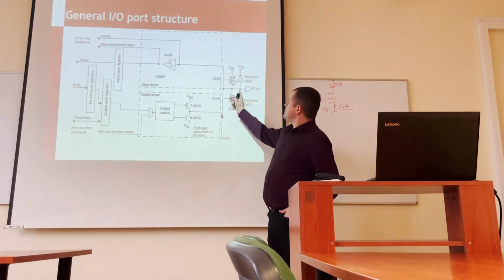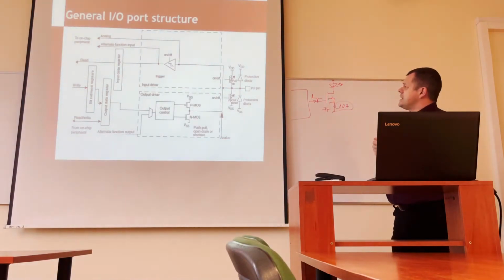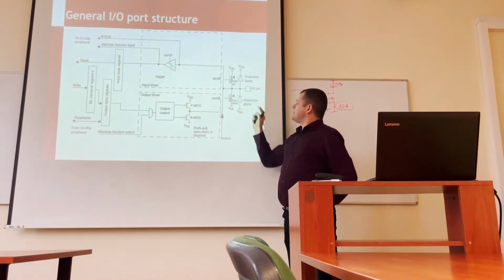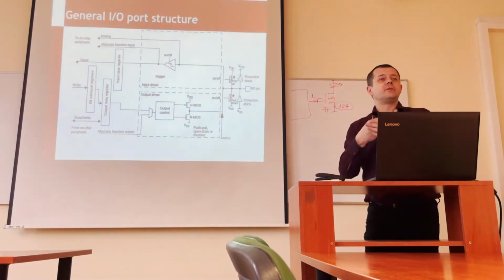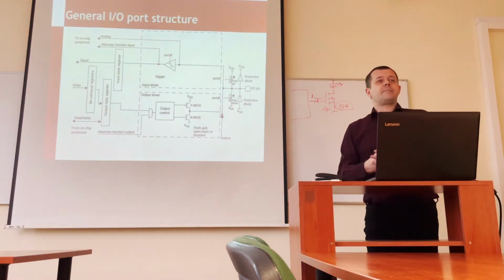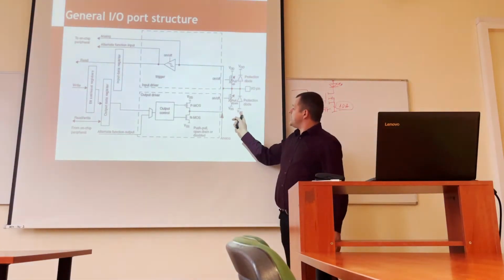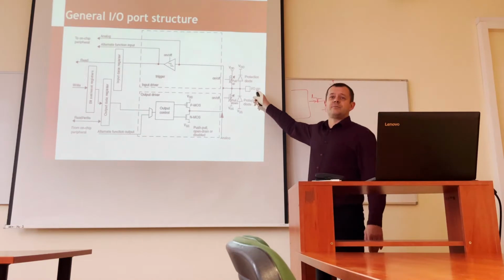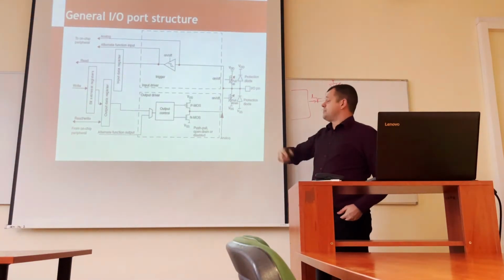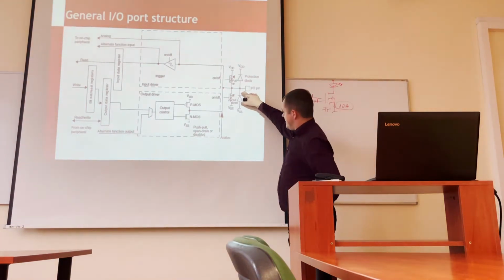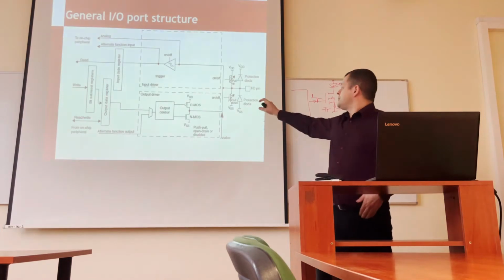Here we have a protection. We talked about it, I think, if I'm not mistaken, previously. So we have these protection diodes. That's why, if you read the maximum limits table in a microcontroller, there is VDD plus 0.2 and VSS minus 0.2, which is the maximum voltage. This is 0.2, 0.3, 0.5, depending on the microcontroller. This is the threshold voltage, the forward voltage of these diodes.